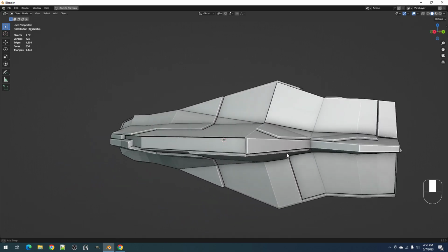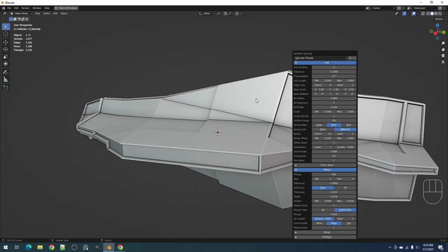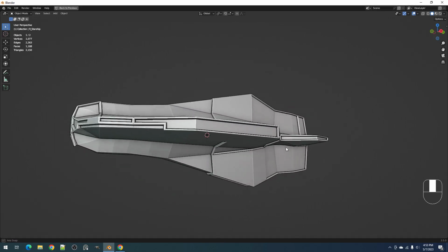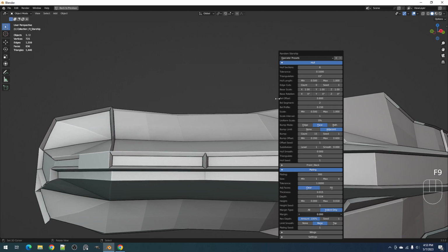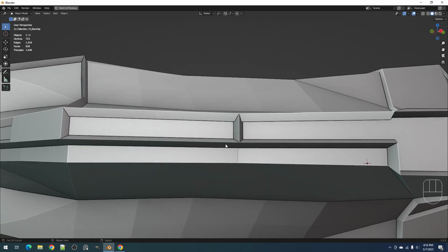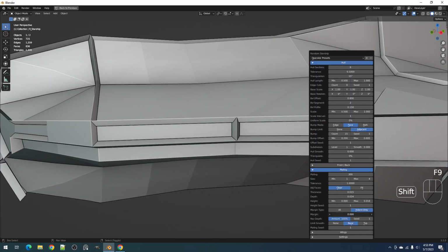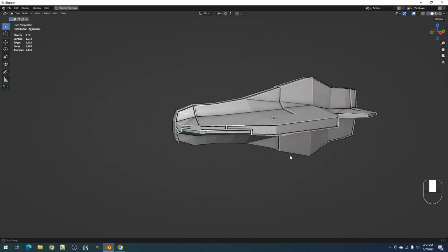Okay, so indent only means that the margin will be created for faces that extrude into the mesh. This is to avoid sharp borders when two of them meet together. For example, no margin, and then you have that. If you're fine with this, then you can use zero margin, but you can just use some tiny amount just to break them apart.